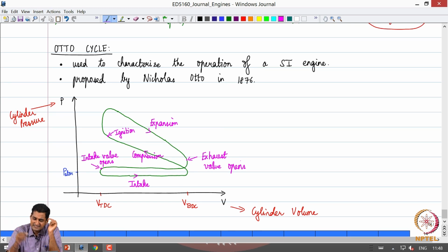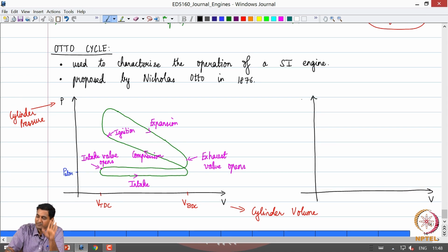So, how is this simplified and visualized in the Otto cycle? In the Otto cycle, which is an air standard cycle, we are not going to be worried about the constitution of the mixture. As I said, we are only going to consider the fluid as air. So, consider a closed piston cylinder combination which has the same quantity of air corresponding to this fuel air mixture.